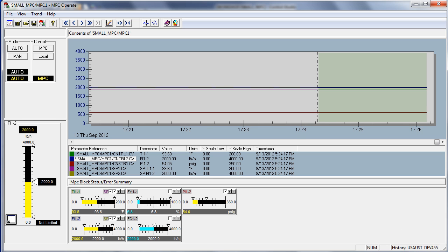The online interface to the operator for simple MPC is shown here. There are controls where simply by clicking on MPC, the downstream blocks are automatically put into cascade mode. MPC can be run in automatic, or auto, manual or automatic control.